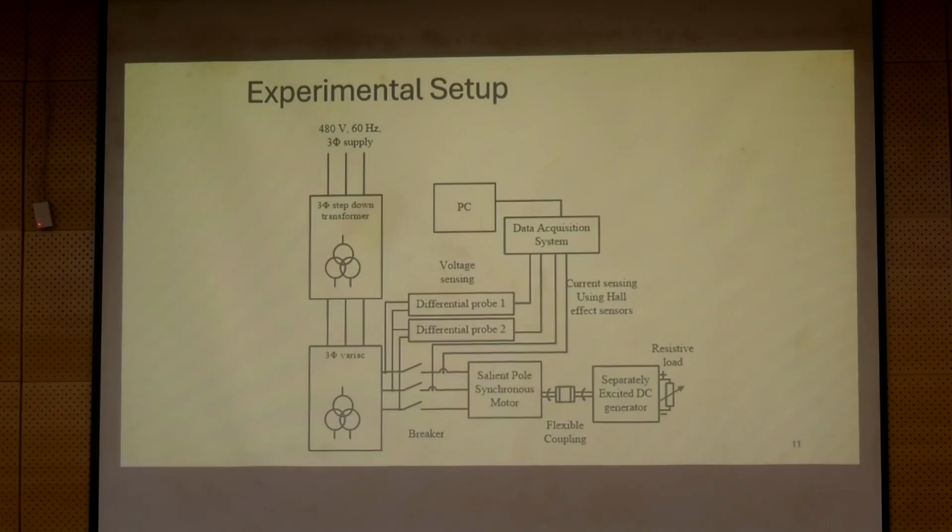So your sampling has to be done keeping in mind the highest frequency component of your interest, and then you have to sample it in such a way that you wouldn't lose that information. So if you sample at a higher rate, you will be able to do that. So a data acquisition system in which you can sample at a high enough rate so that you can capture some of the lower order harmonics of your currents and voltages would be quite helpful.